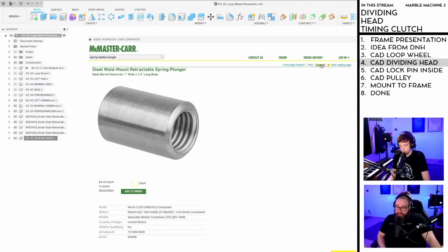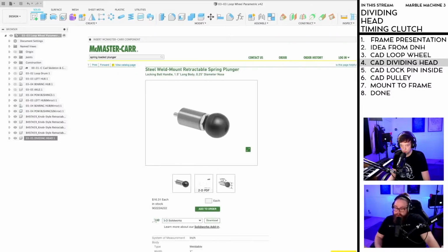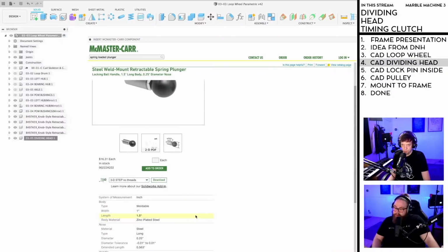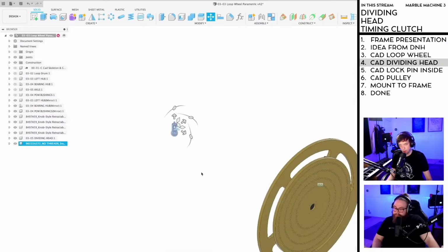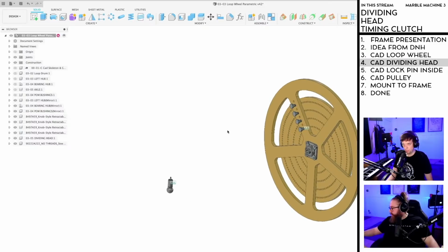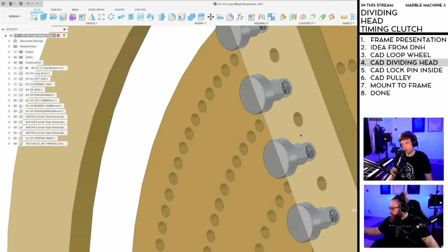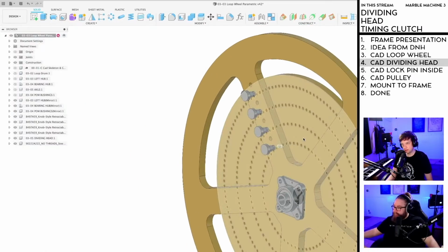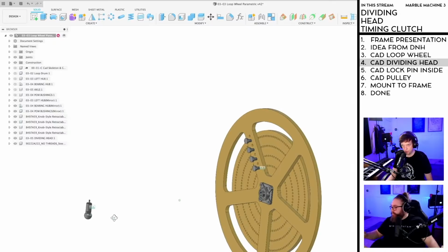Alexander Sola, shouldn't the holes be 8.1 millimeter or 8.05 millimeter to allow for clearance from the bolt, which is 8 millimeter? Yes, probably. I am doing this kind of low resolution. If you mean these holes, here. Okay, yeah, I see what you mean. It's a good point.